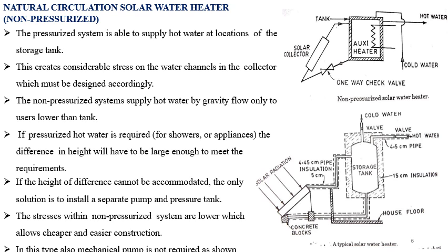Alternatively, a slow reverse flow of the warmer water may be permitted through the collector on cold nights. The freezing danger can be overcome, although at some point it will increase the cost, by using an antifreeze solution as a heat transport medium.